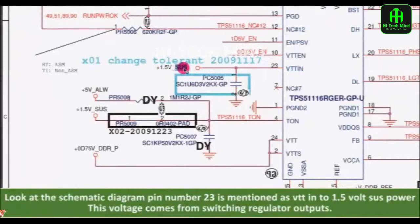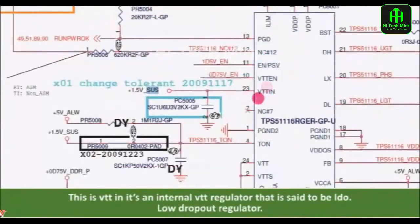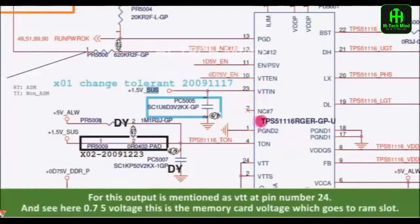This voltage is coming from the switching regulator outputs. This is VTT in. It's an internal VTT regulator, which is said to be an LDO, low dropout regulator. The output is mentioned as VTT at pin number 24.